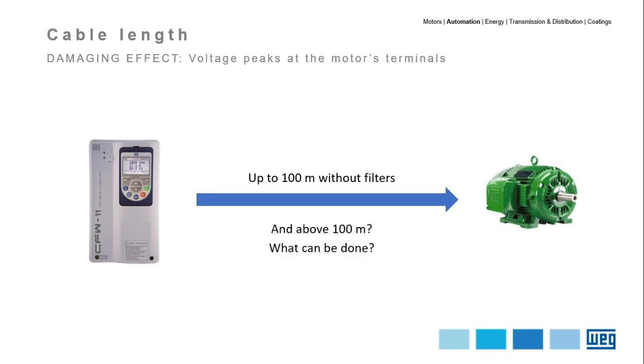WEG induction motors to be driven by VSDs, or WEG VSDs, are designed and constructed to withstand the PWM effects in applications up to 100-meter long cables without any additional equipment. But what about applications with longer cables than 100 meters?